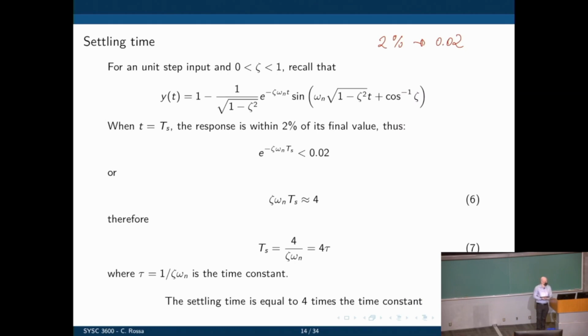Now let's look at the time response here. The time response has a constant one that comes from the step input. That's where the system is going to eventually settle. And we have an exponential times a sinusoidal. The sinusoidal waveform is always there as t tends to infinity. But we have an exponential component that is decreasing over time and making that go to 0.